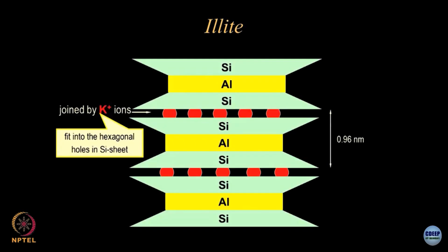It is another interesting mineral where the spacing between the alumina silica alumina sheets would be filled up with potassium ions. So, normally potassium ions go and sit over in between, and again this is a very weak bond as compared to the hydrogen bonding or van der Waals forces. So, this is how the mineralogy is taken care of.